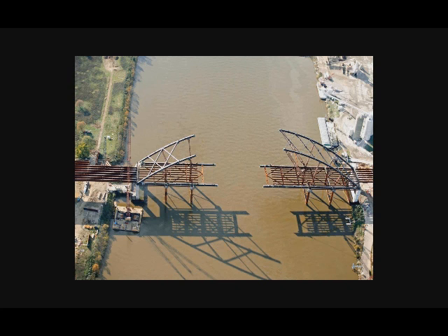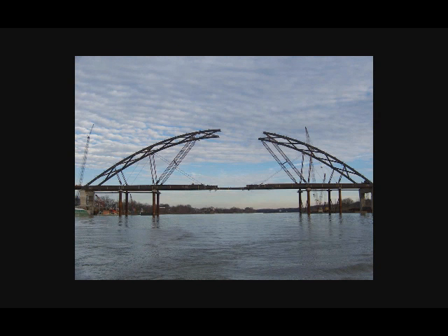Moving right along, so here we have the second half erected. You can see the shoring system and the channel for traffic to pass through in the middle. And then it gets interesting because now we have to close the two arch halves. And there's always the excitement, will the last piece fit? In this case, the contractors made sure it would by building one of the arch halves about 6 inches off center, moved towards the abutment.